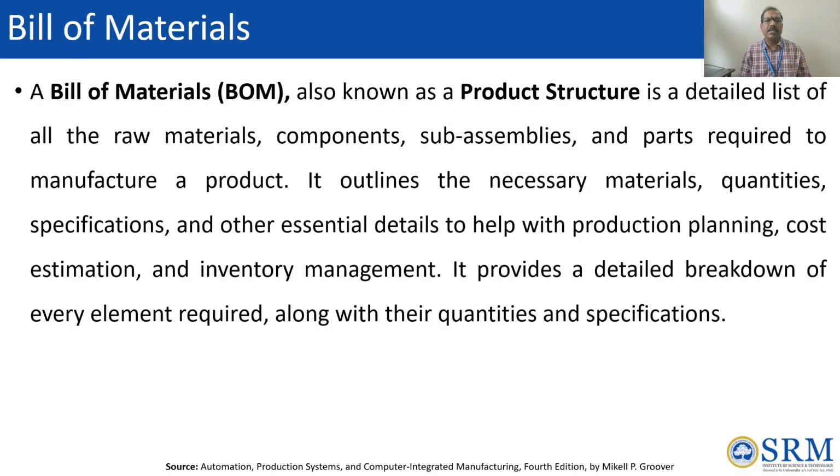The table discusses the components, what parts are available, what angle of projection is used, like first angle projection or third angle projection, and who created that engineering drawing, which company it belongs to, and the name of the part. That is the bill of material in terms of engineering drawing, right?